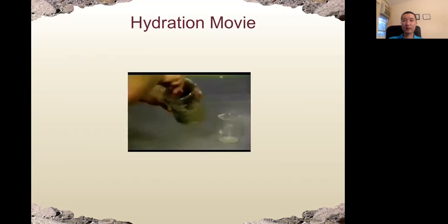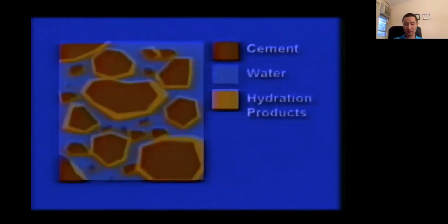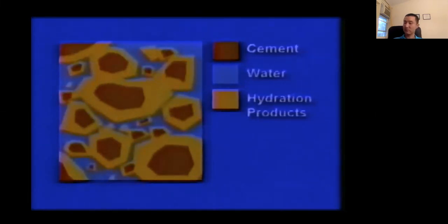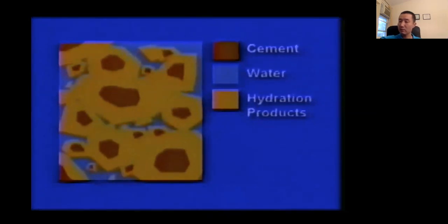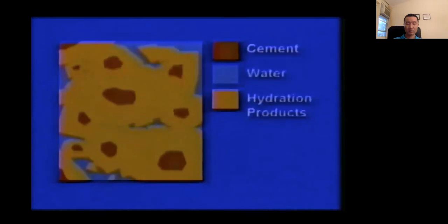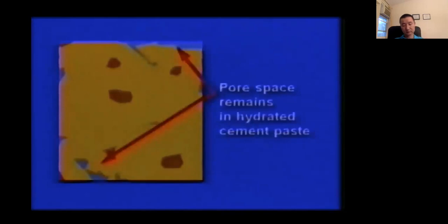So this is a short video talking about the hydration process of concrete. This is a sketch of cement grains suspended in water. The solid hydration products form coatings around the particles of cement and gradually fill the space between. When the coatings first begin to impinge, setting occurs. There is a steady development of strength as the coatings grow together. The amount of strength attained by the mixture of cement and water depends on how effectively the space between the grains is filled up. Concrete will harden within a few hours, but hydration continues for weeks, even years after placement.